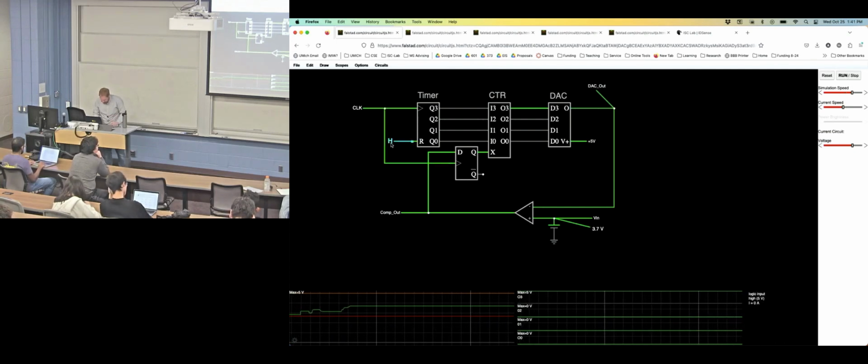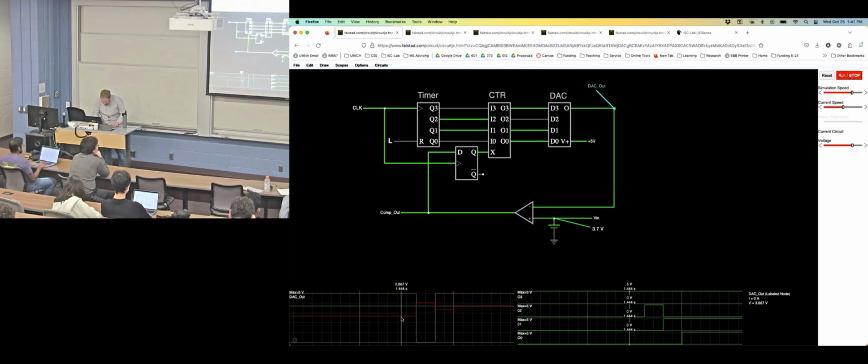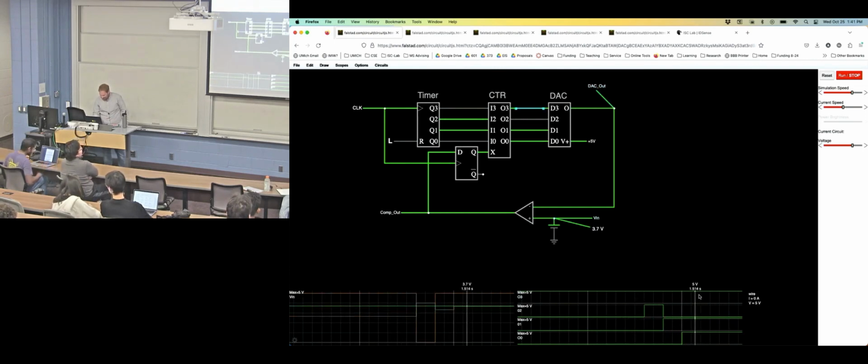So I'll turn it on. And here we're going to make a decision. You can see the search. This is only 4 bits. So we searched here. We went to that high bit. It was too high, too low, and then we got to a value that's pretty darn close. And then you can see the binary value out here of what equivalent digital value is for that analog input.